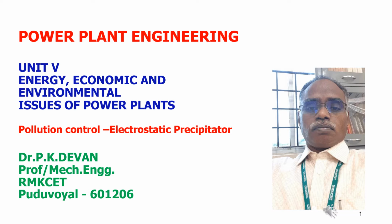The common methodology used in major power plants for pollution control is the electrostatic precipitator, which controls nearly 99% of the pollution, but it is not suitable for high resistive fly ash. In that case, after going through the electrostatic precipitator, we have to make it go to the wet scrubbers also. But most of the fly ash will be filtered by using the electrostatic precipitator.